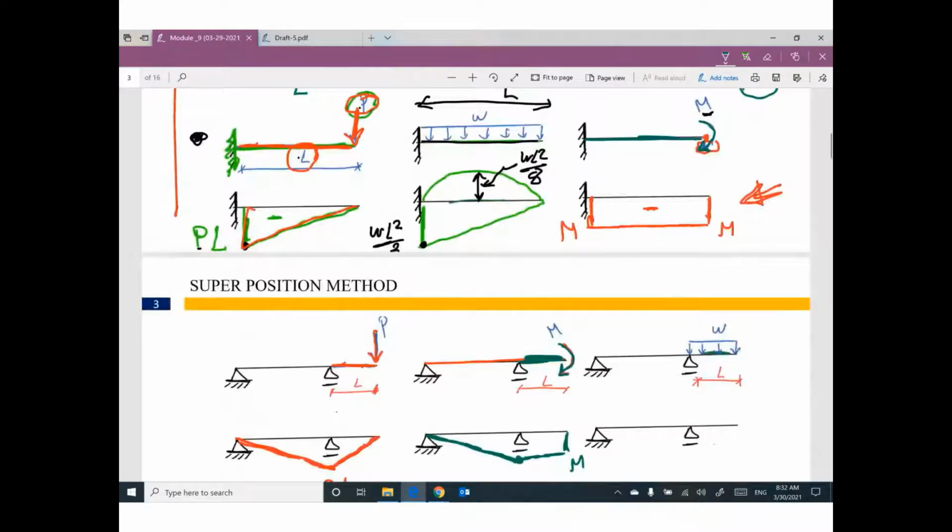Okay, what will happen if you have a uniform distributed load? The uniform distributed load on this part looks like the uniform distributed load on this part of the beam. So I expect we will have a triangle W L square divide 2, and I expect a parabola, this value W L square divide 8. Once you are done, the last value connect it to 0. That makes sense?